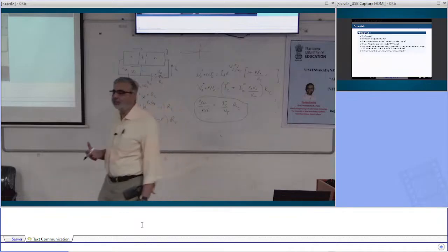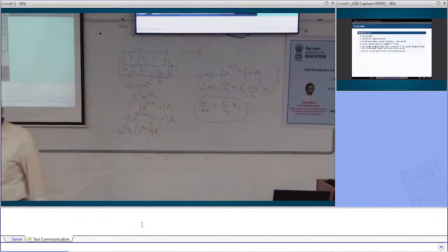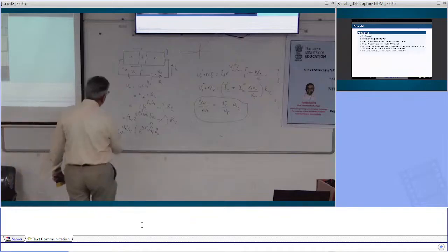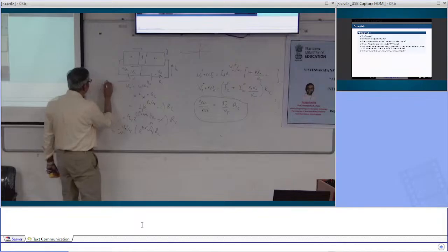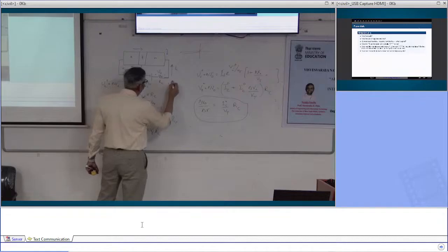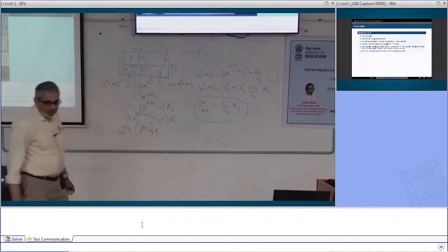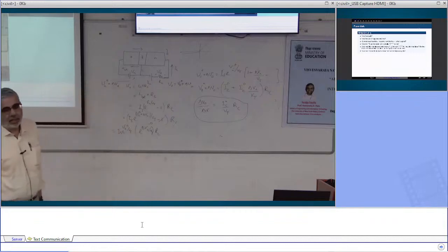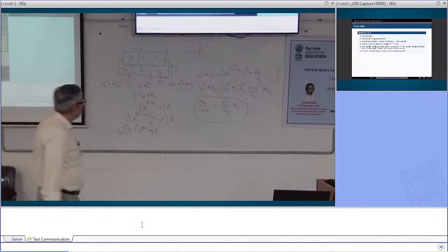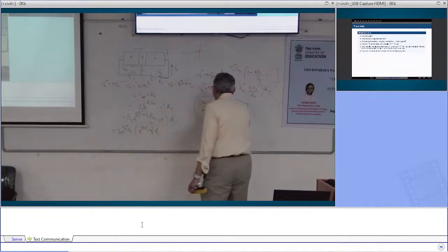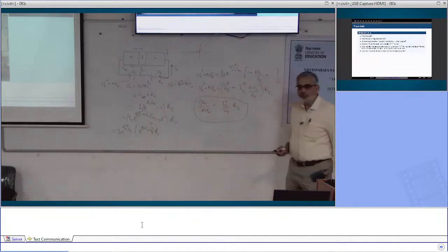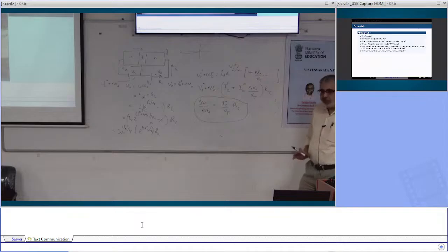So IC0 is the bias current. I didn't want to get into that, but there is no option. So that is the current due to the voltage VI0. So this voltage is VI0 plus delta VI. This voltage Vout is Vout0 plus delta Vout. Okay, so I'm looking at the change in the output voltage due to the change in the input voltage. And that's the expression I get.